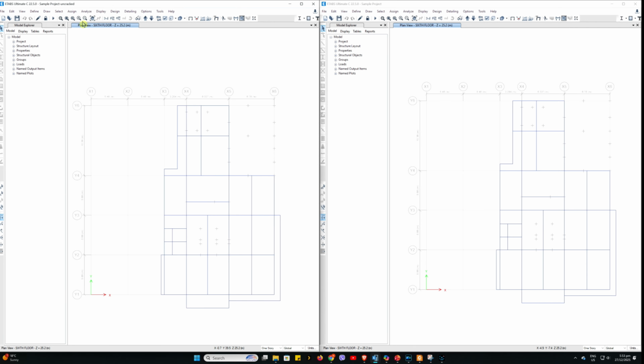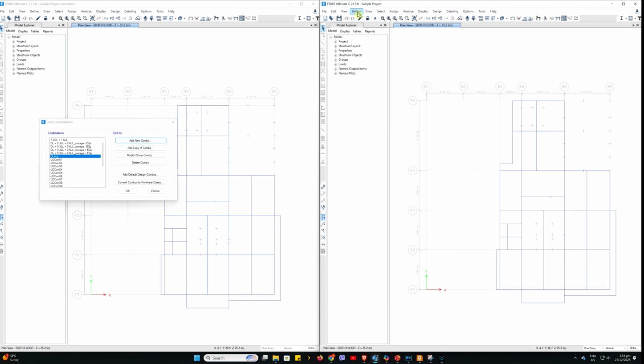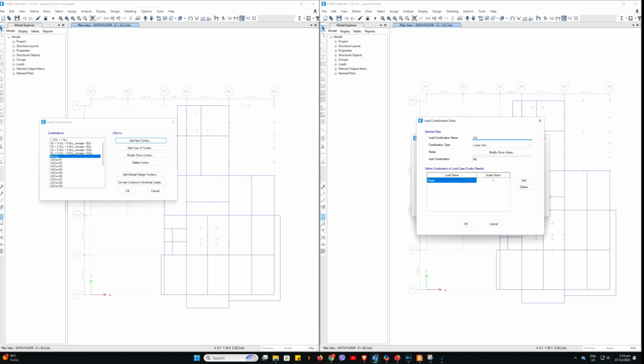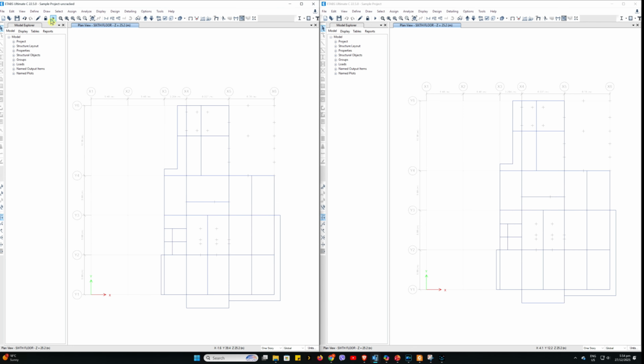For example, I have taken a couple of identical models, except beams and columns are assigned stiffness modifiers in one of them. In other ways, like loading and modeling, they are identical. As you can see, their base reactions for earthquake loads EQX and EQY are the same.